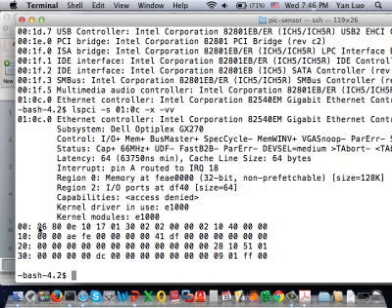So let's look at this. If you remember the table I just showed you, the first two bytes represent the vendor ID. And this is little endian, so we're talking about 8086. Every vendor, let's say Intel or AMD or NVIDIA, will have their own IDs, and these IDs are managed by the PCI SIG organization. That's the authority to assign these IDs. And 8086 is the ID of Intel. So we know this device is manufactured and designed by Intel.